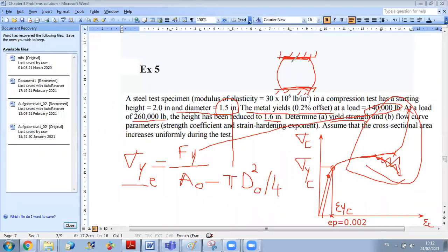This is why, as a first step, the dominant effect will be the transition from elastic to plastic, which makes it a little easier to deform. This is why the slope decreases first. But after, the resistance effect at the plate level will be dominant. This will cause a re-increase in the slope until fracture. Okay, so this is how we do the analysis of the inflection point in the engineering curve.